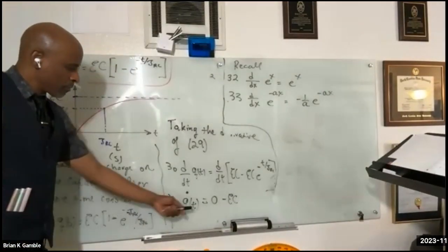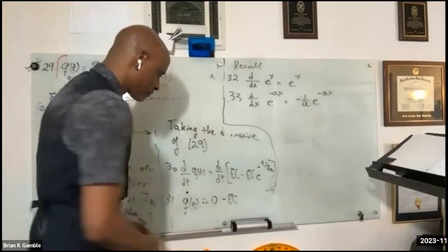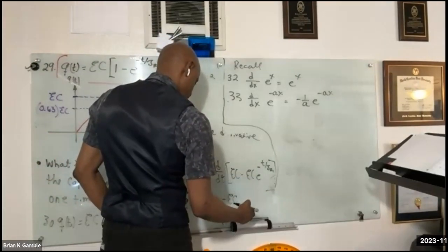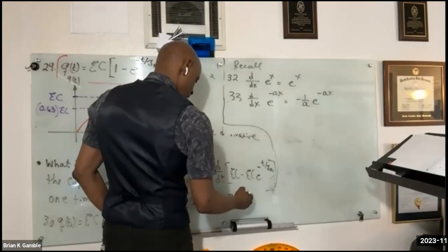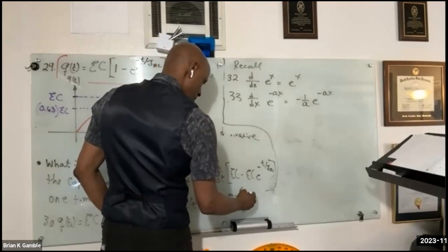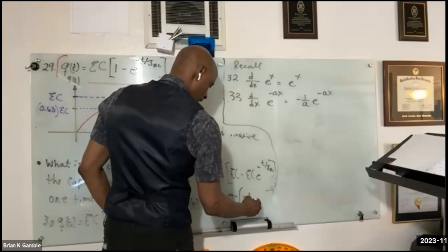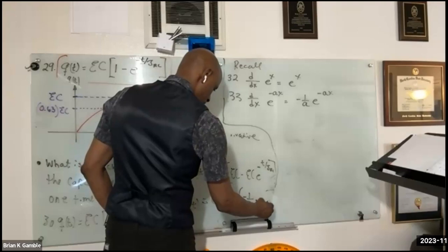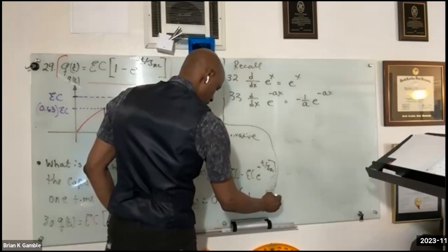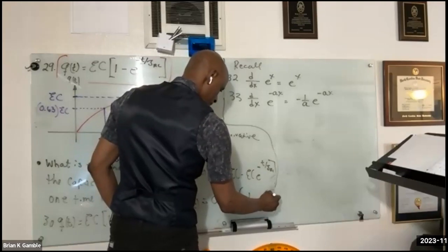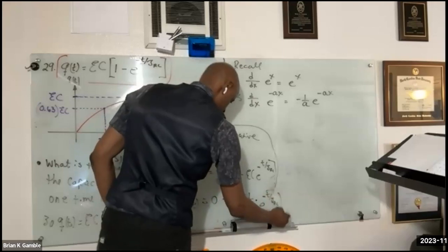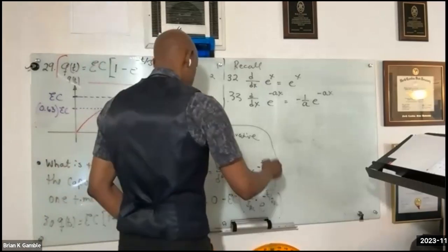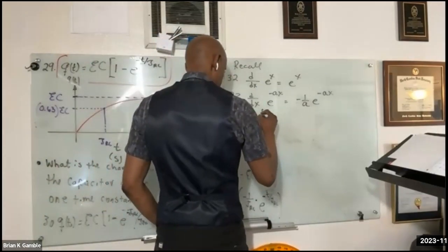All right, so I'm going to apply that here in this term. So what that's going to be is I have a minus sign out there already. That's this guy. But then that's going to be times -1 over tau_RC times e^(-t/tau_RC). So the minus and the minus cancels.